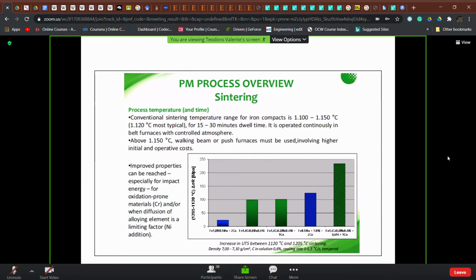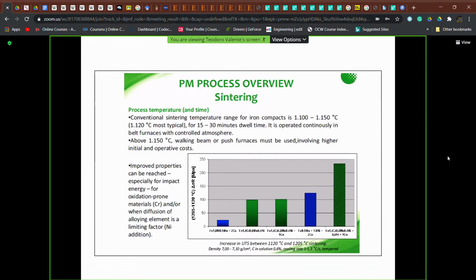But in both cases, we have inside the very simple formula of the monodimensional Fick law the diffusion coefficient. And if you remember, the diffusion coefficient has an expression like an Arrhenius law, and it has inside, apart from the Neper number, the temperature. And how high is the temperature? So high is the value of the diffusion coefficient. So high is the diffusion phenomena.